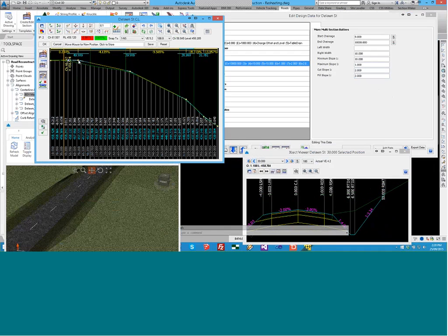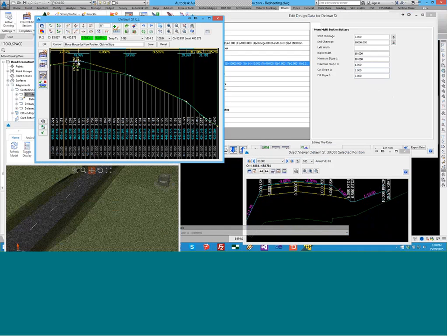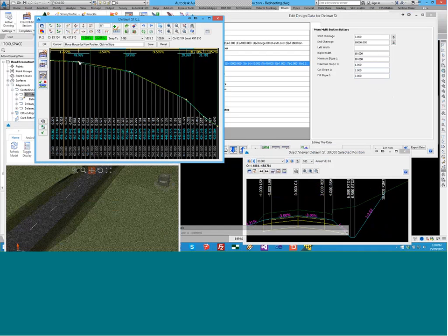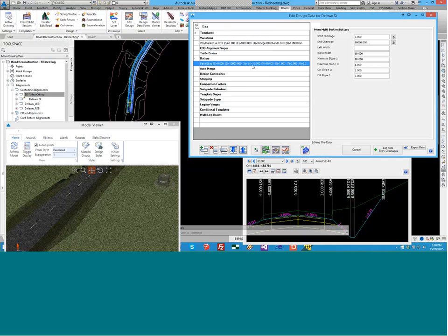But when the batter forms within the slopes we want, the minimum maximum slope, then that's good, it'll form. But if we're outside those slopes, then that second leg is formed to match to the surface. Okay, so if you hadn't seen that one before, I just wanted to quickly show you the dual leg batter as well. So let me just delete that.